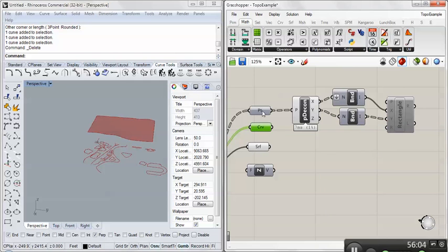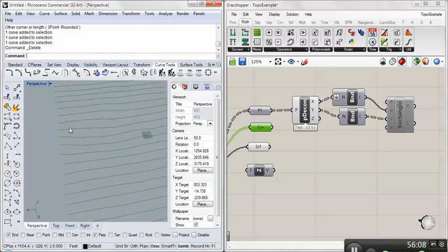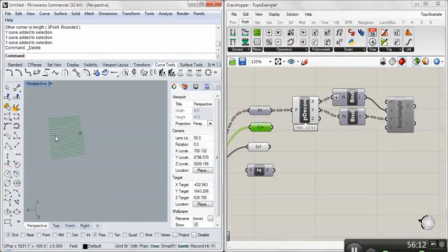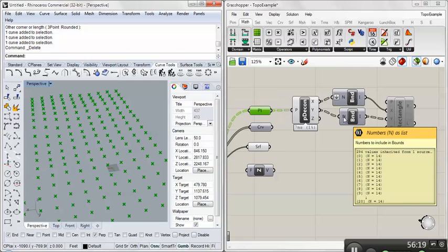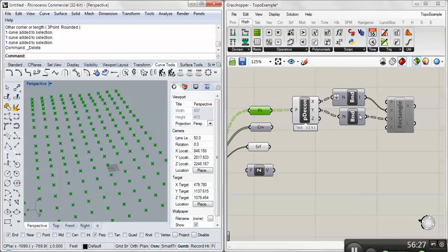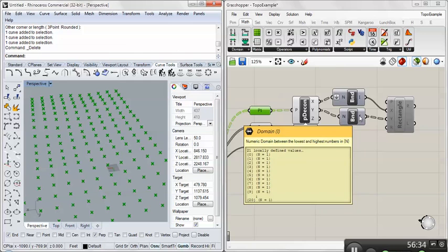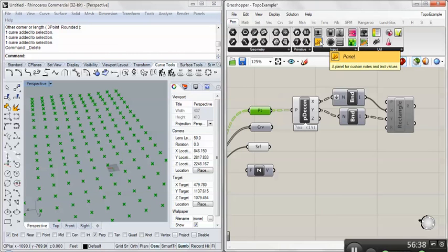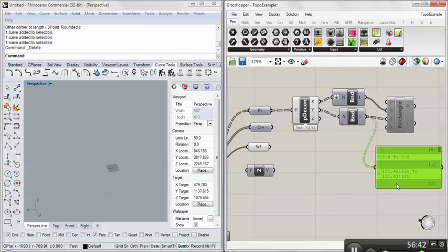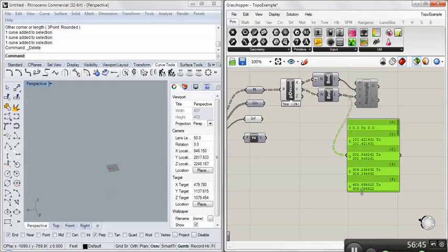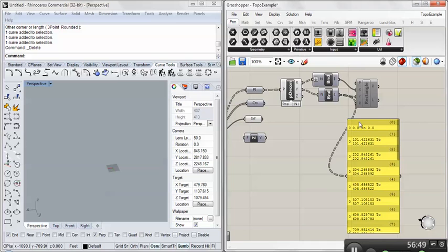In this case it's the curves. I have 20 curves here, 20 rows, and then each curve has a certain number of points in it. When I did the min-max here for the structured data, it said, oh, you want the min-max for each row. You don't want the whole group. So if you look at the output here, again, it's in this sort of notation for array notation. But you can always look and see what's going on inside under panel. So here I have every row min and max. And since this is the row data, there is no difference along that whole row. Every value has the same Y. So the min-max doesn't mean anything here.